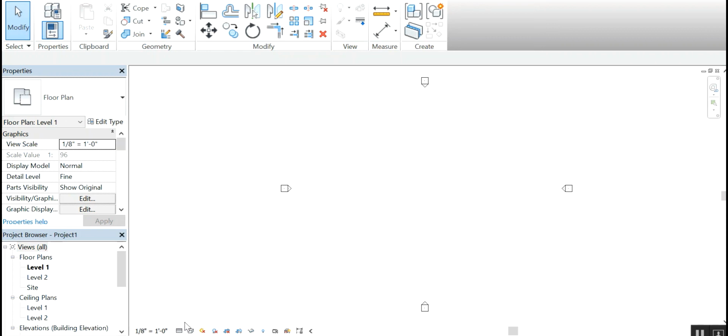I like to see as much detail as I can, so in all my views I turn on the fine resolution. I think the reason Revit is set for the coarse resolution to be turned on by default is simply the more resolution you show, the more memory it's taking up at any given point in time. But I've never had any kind of memory problems on my computer just because I have the fine resolution turned on at any given moment. Okay, so that's all I wanted to cover here.